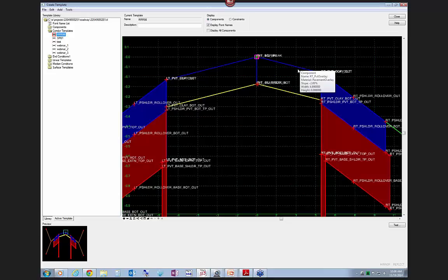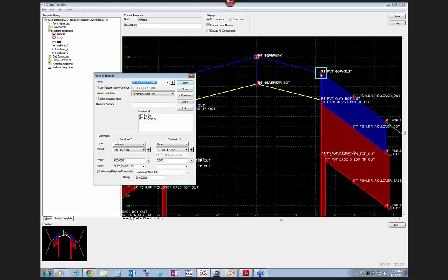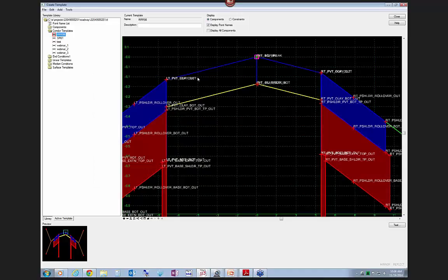There's lots of other ways of doing this, but that's the simplest way. If you want to match existing between 2 points on your surface, you set this to project the surface and project it to the active surface, and that will do the match existing. Otherwise, you leave it at a slope constraint and it does the cross slope correction.